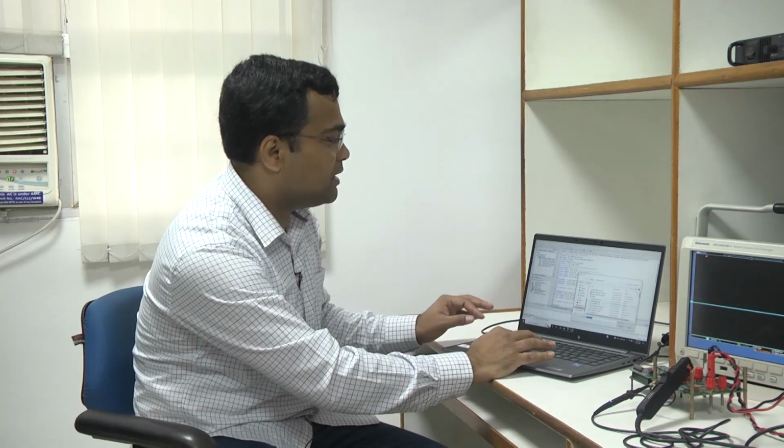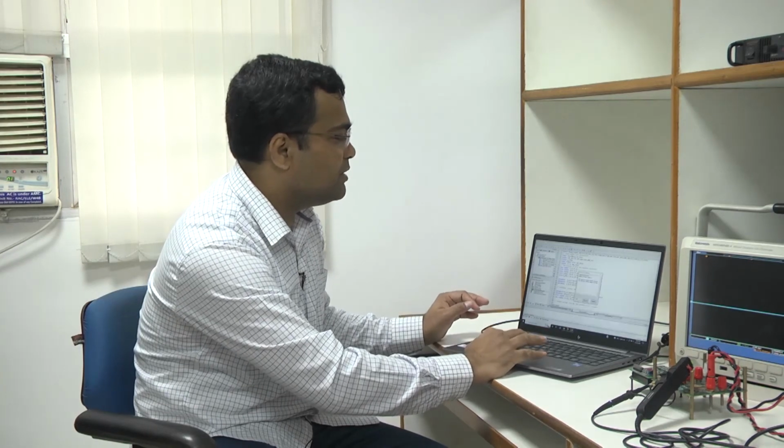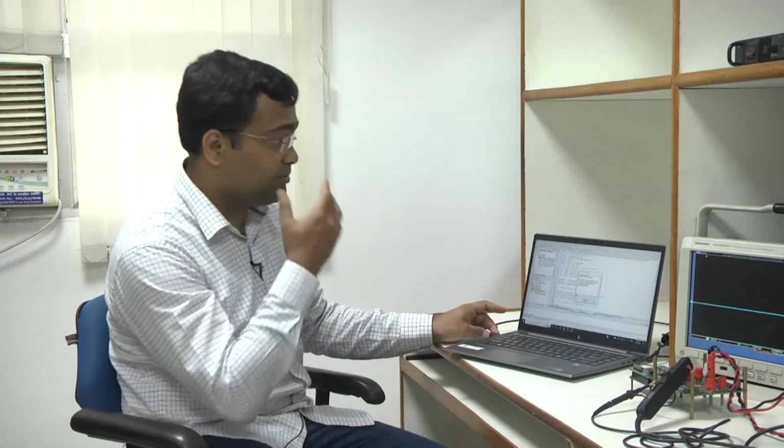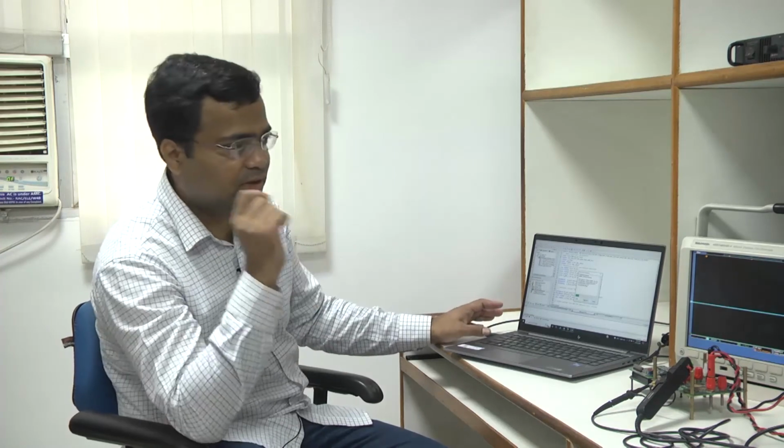Once we run this code and the program file is generated, we have to select this particular bin file, then we need to program it. It will take some time, and once this programming file is dumped into the flash memory of the FPGA, we will be ready for running the actual hardware.